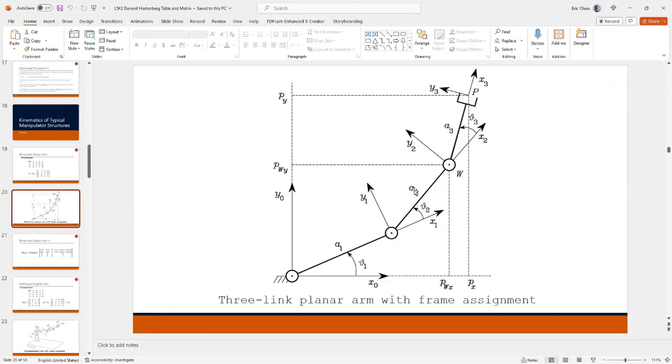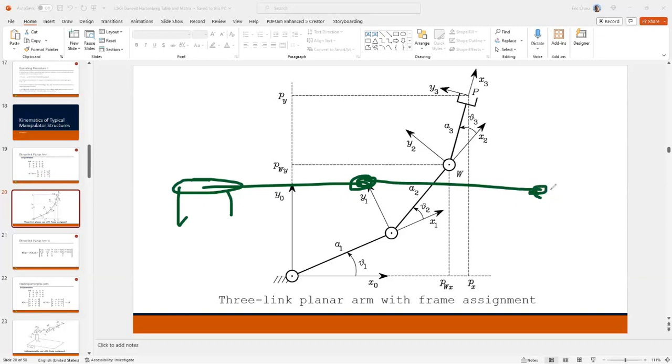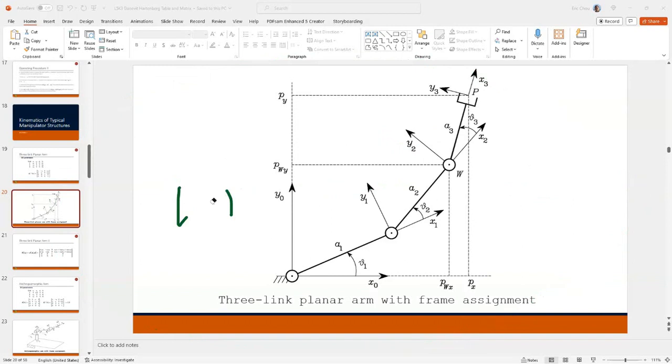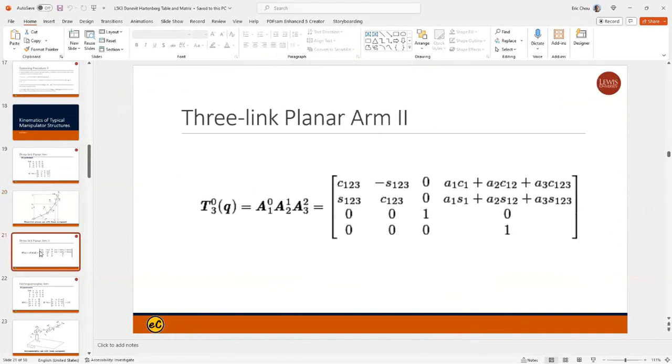Planar means that you have 3 joints, but no matter how you swing your arm, it will be on one surface, because you have a rotator in the middle. Your arm is just rotating in a 2-dimensional space. It cannot go up or down, it's only XY change. There are 2 degrees of freedom.